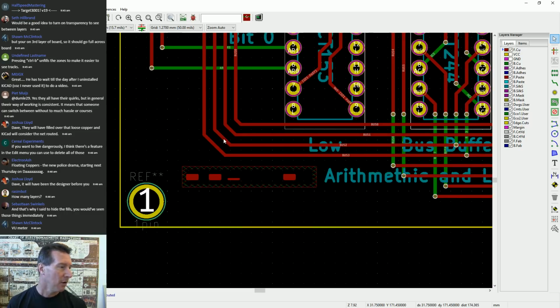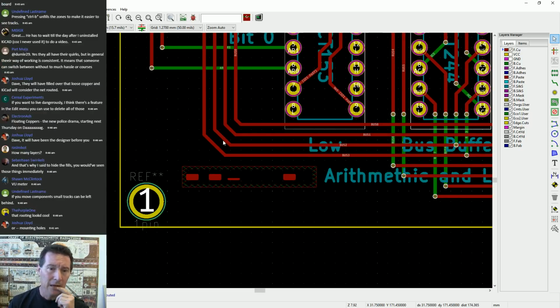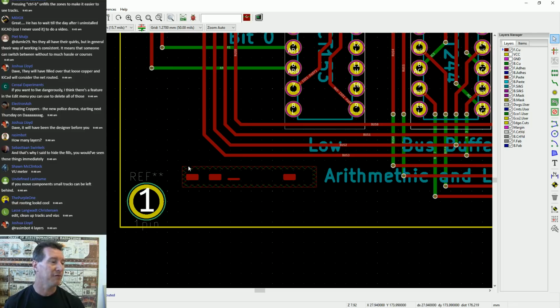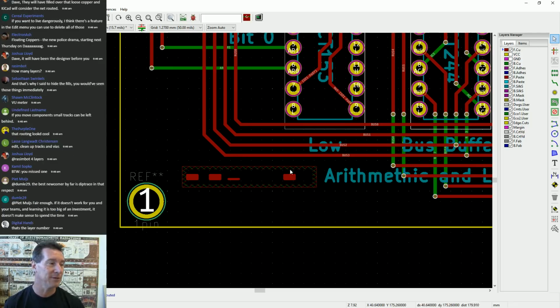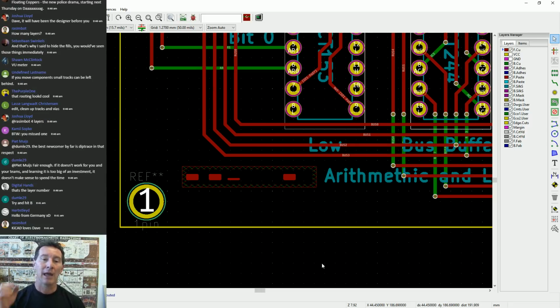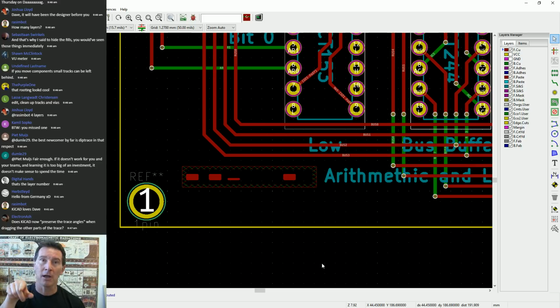For those who don't know, you'll usually do this outside the board. You usually won't do it on the board because it's just visual pollution. Well, some people do, and it's fine. You'll have a test coupon. It goes by various other names, but you'll generally put it on the outside of the panel, and you'll put things like the minimum trace width that your manufacturer can do. So you'll put a couple of lines on there to set minimum trace and space and stuff like that. And you might put some alignment markers, or some silkscreen over the copper, for example.